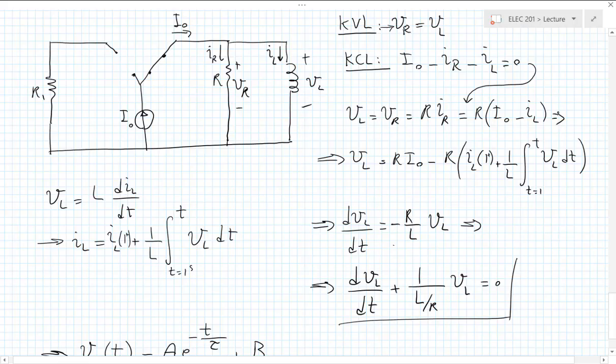the current, right? Because that would require an infinite voltage, which means before the switching, as we know, there was no current. We had it somewhere up there. After the switching action, so at t equals 1 plus, the inductor still hasn't changed its current, doesn't like it. So the current of the inductor at t equals 1 plus is 0.